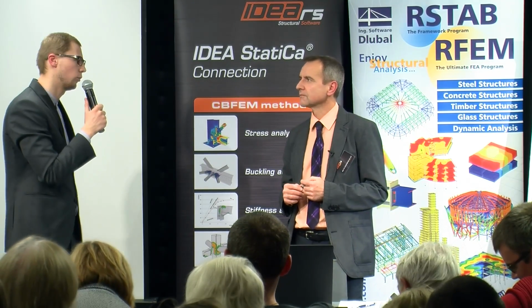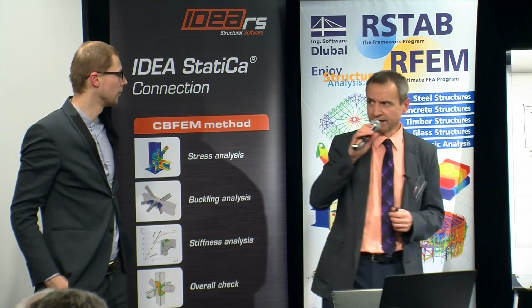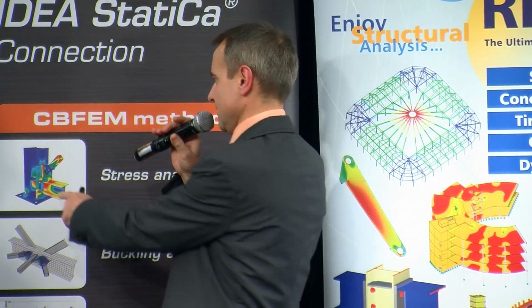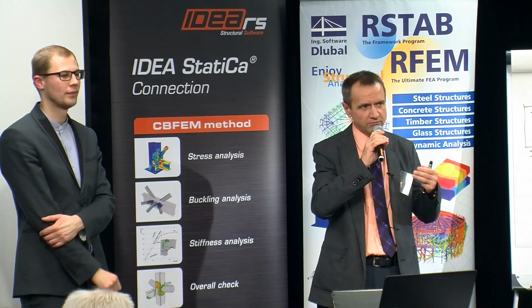Okay, the question was, the software you showed, is it possible only to calculate, or is it possible to model as well? Actually, if you mean by modeling that we have the possibility to produce drawings and to model the geometry of complex 3D structure, then no. But on the other hand, we have, of course, our input and our modeling. If you have a 3D beam with various cross-sections, with haunches, changes of the cross-section, you can, of course, model it in our standalone program. Also, the steel connections, you model it in a way which you cannot model in other software. You can really make such a joint in 10 minutes to input it, and it speaks, I would say, your language, because there are manufacturing operations. So yes and no. Yes, for the applications which we really support, beams, cross-sections, and details. No for complex 3D structures.